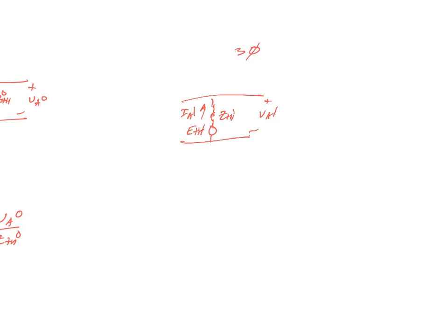So essentially what we're saying there is if you really want to just solve for the positive sequence current, because IA2 is going to equal IA0, which is going to equal 0, because in a balanced three-phase fault we don't have negative or zero sequence. So you can pull out the Z-bus parameters and calculate what those values need to be, and it makes it very, very simple to do that.